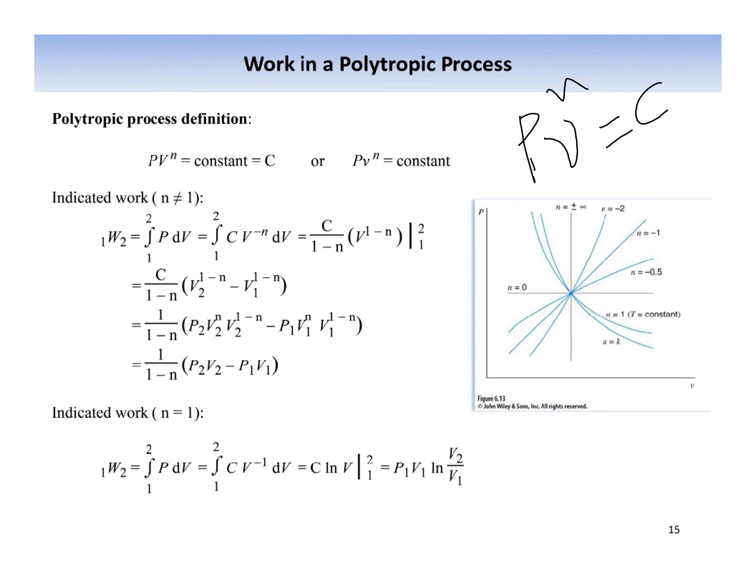And we can use the formulation, if you know the behavior of the system, for instance that pressure has a linear relation with the volume during the process of transforming from state 1 to state 2. We can use the work formulation which is being derived over here, and these are two formulas that we can use to quantify work, if we know the relation of pressure with respect to volume.